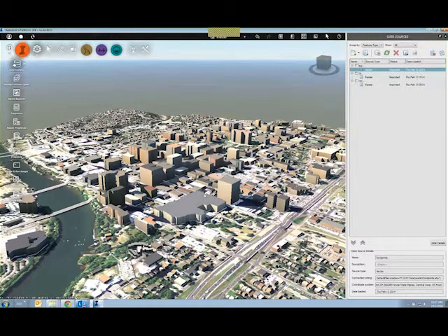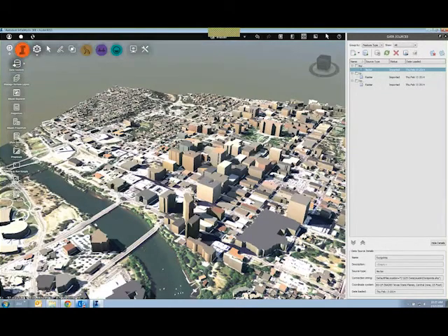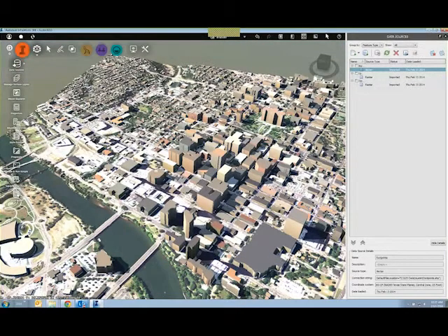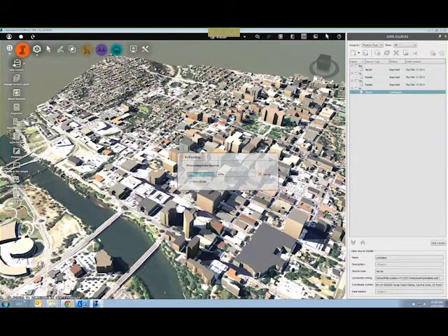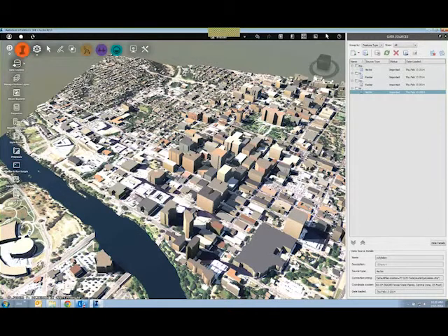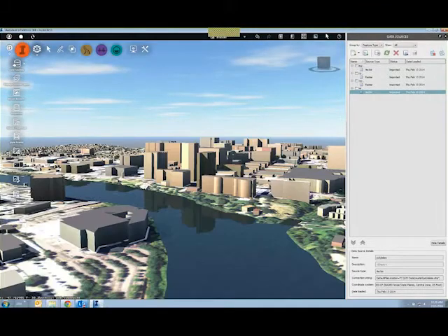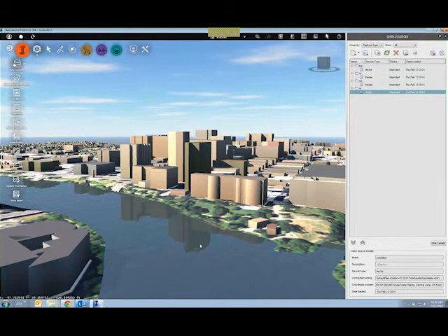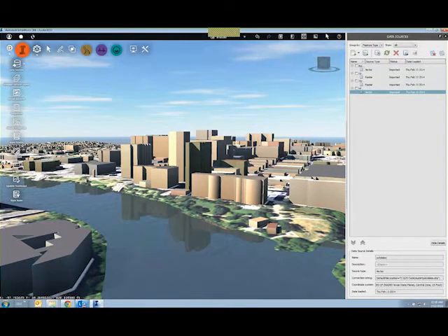I've got some lakes that I want to drop in, so the water bodies, and I'll tell InfraWorks that this is a water area. Again, close and refresh, and you'll see that the roads just got flooded out. But with InfraWorks, we do present a very nice view of water. You can see we've got some nice reflections going on. Is it 3ds Max style reflections? No. But is it the sort of reflections that I look at and go, oh yeah, there's water there? Absolutely.